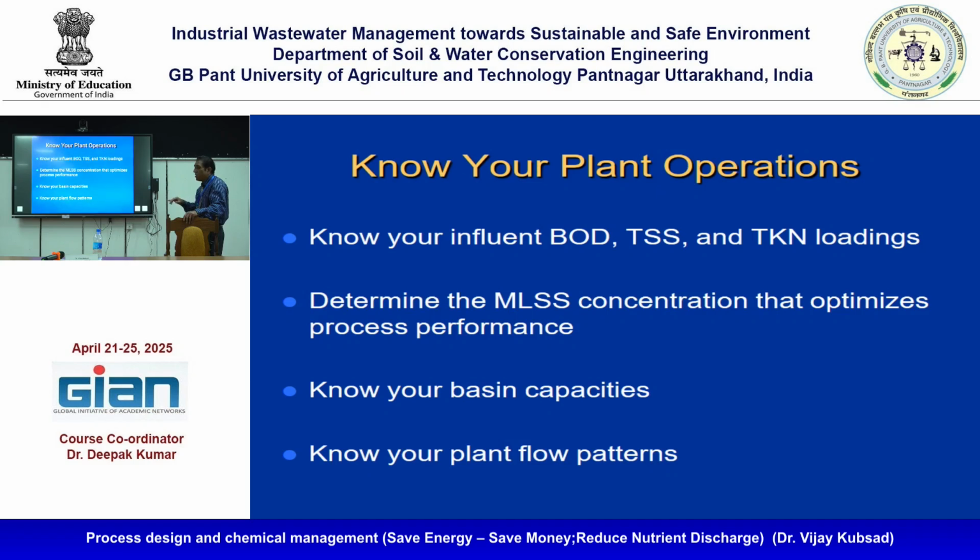So determine MLSS concentration and optimize process performance. See whether MLVSS, meaning the bacterial load, exists or not. If the bacteria are not there in sufficient concentration, at a rate of 2000 to 4000 in the aerobic treatment, how can we expect the effluent quality?